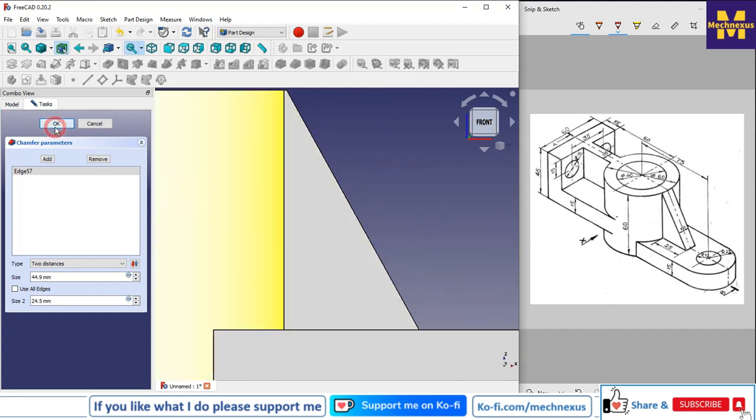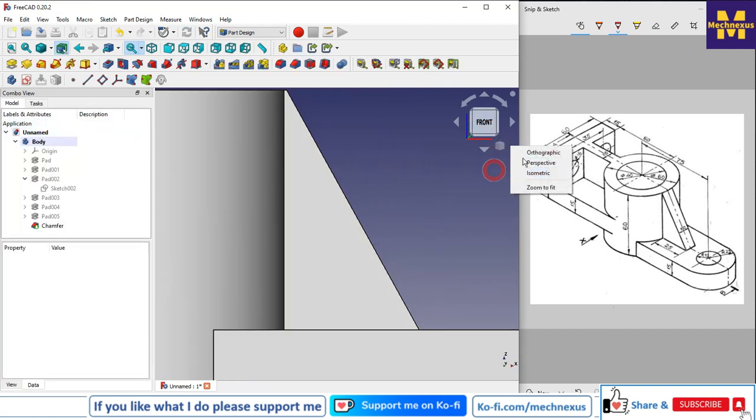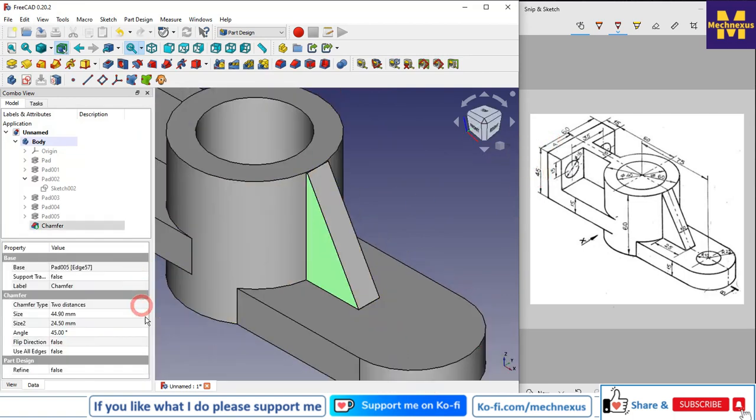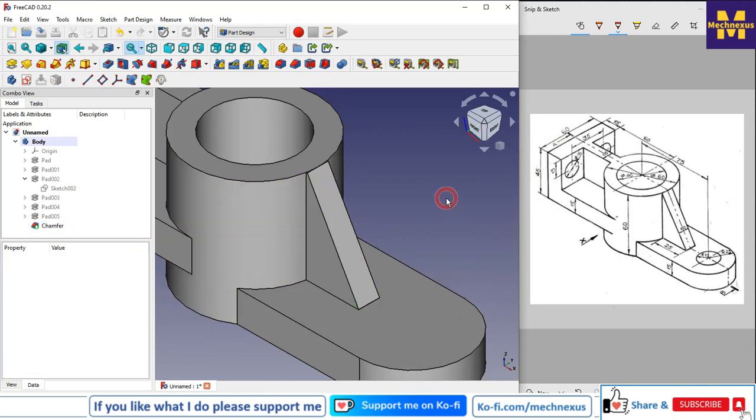Now I will say OK, or you can simply create a sketch on this face and remove the material, but that's good, we have learned something new, the two distance chamfer in this part model.